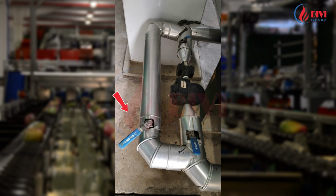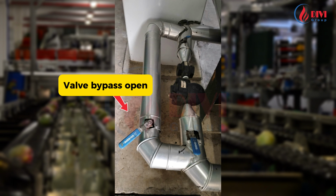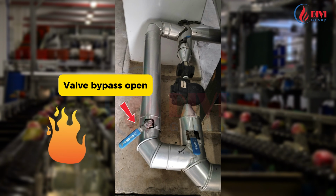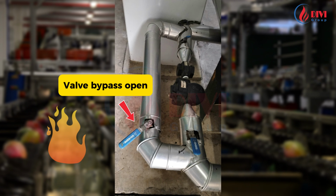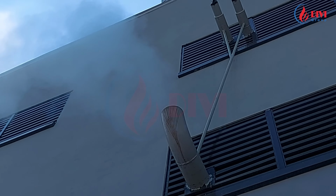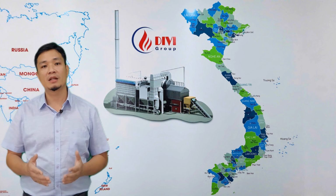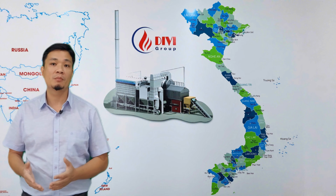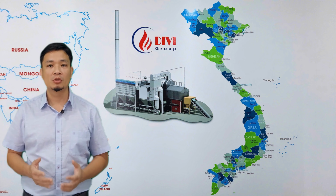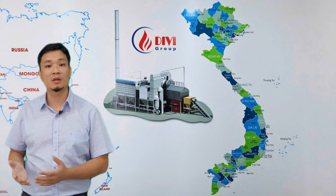When condensate backs up, operators often open the bypass valve to heat up the equipment faster. However, once the bypass is opened, steam flow rises suddenly, and many operators leave the valve open. This causes a large amount of steam to return to the boiler. Regarding how to select steam trap discharge capacity, please rewatch the previous video, Understanding Steam Traps, Part 2. I provided a specific example in that video.